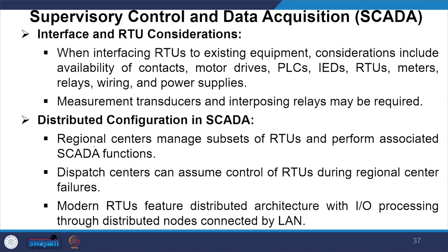When interfacing RTUs to existing equipment, considerations include availability of contacts, motor drives, PLCs, IEDs, RTUs, meters, relays, wiring and power supplies. Measurement transducers and interposing relays may also be required.